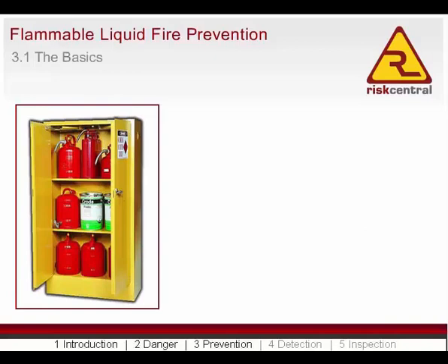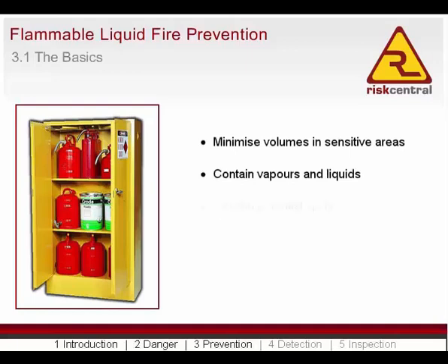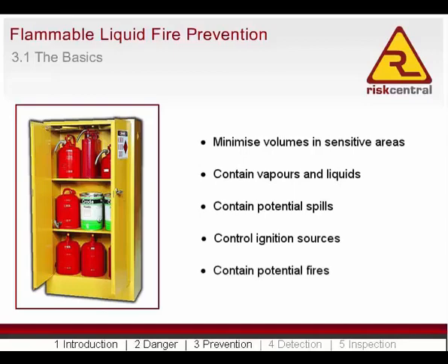Following some simple storage and handling precautions can avoid most flammable and combustible liquid fires in typical occupancies. All the following controls revolve around some basic principles. Minimize volumes in sensitive areas. Contain vapors and liquids. Contain potential spills. Control ignition sources. Contain potential fires.